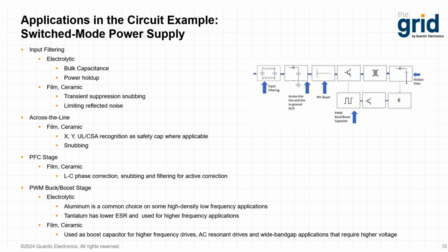Both film and ceramic capacitors can be used in this stage for transient voltage suppression and limiting reflected noise and any EMI-related applications. Additionally, due to their ability to be manufactured as a safety capacitor, that is, a capacitor that fails open, both film and ceramic capacitors can be used for high potential line-to-line or line-to-ground applications. In many commercial applications, a safety certification or recognition from a certified body is required for that, such as a